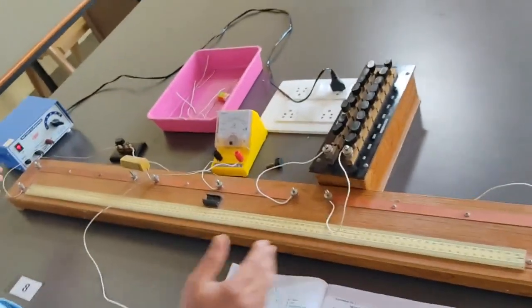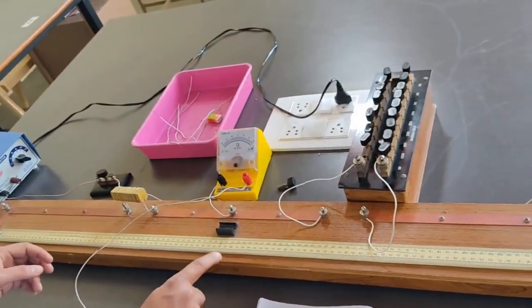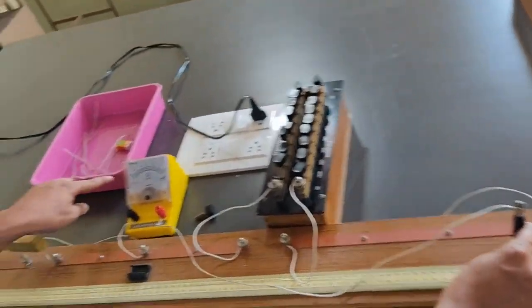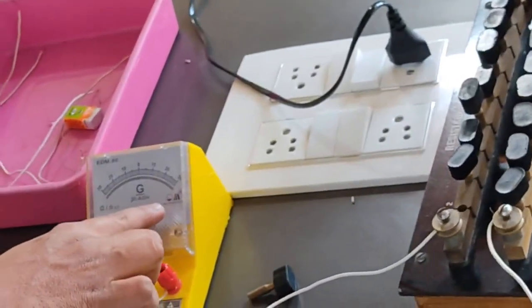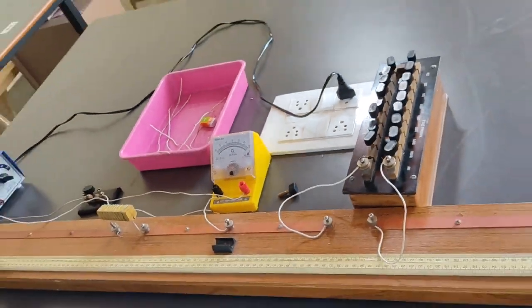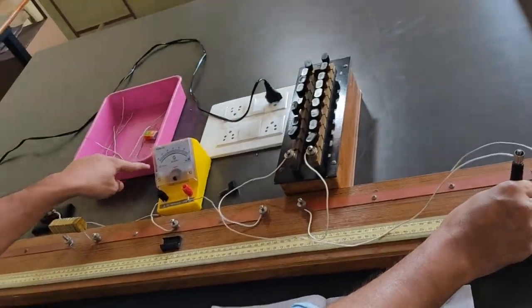Means we have to check either side opposite deflection, because at one side we are going to get zero deflection. So let us check that symmetry. If I keep here, I should get deflection on this side. If I put this pointer or jockey here, I should get deflection this side. Okay, this shows opposite deflection. By putting this jockey here, I got deflection opposite side.